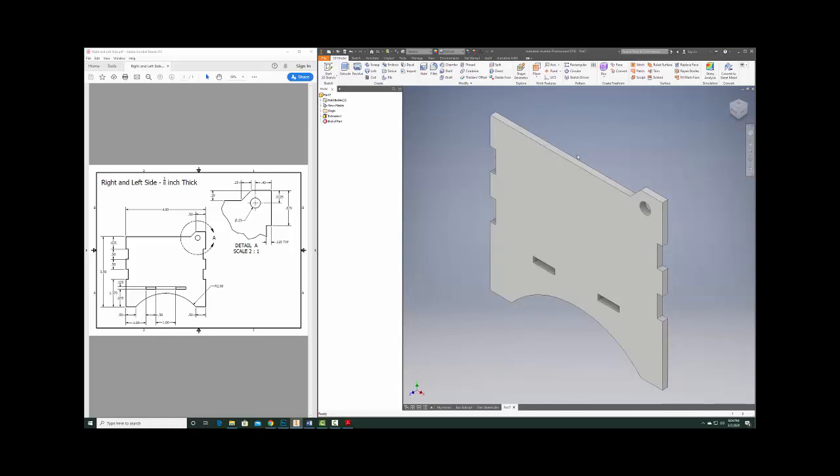If I made a mistake, and I make mistakes all the time, you can go back and fix them. So if I made a mistake in the sketch, like, oh, I got something wrong, I could actually go ahead and click this down and expand the extrusion. So over here, this is called the browser, and it keeps track of everything you do, the order and so forth. So by extrusion, that was me pulling it out to 1/8 of an inch.